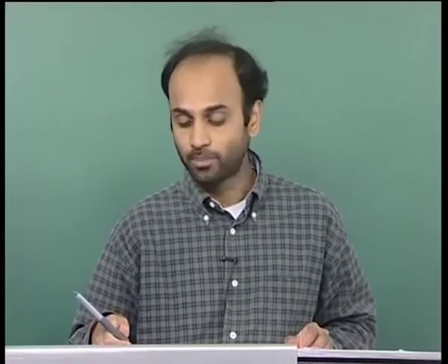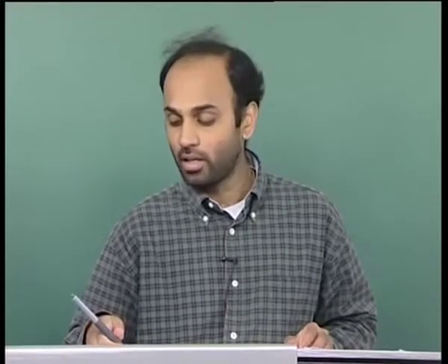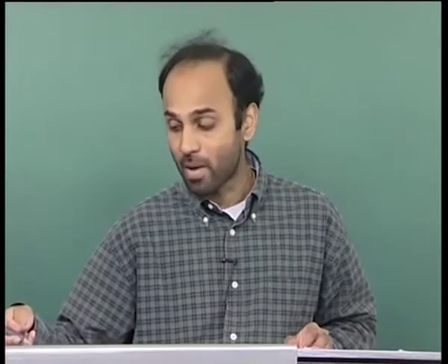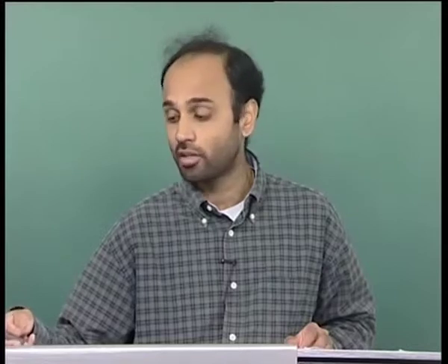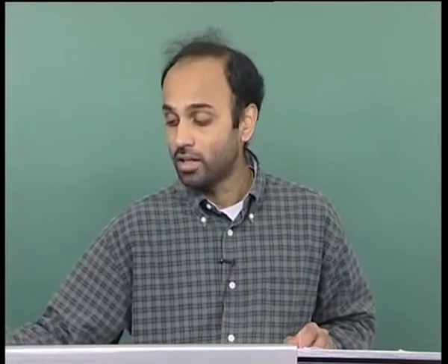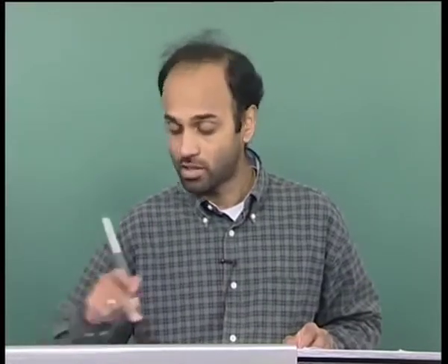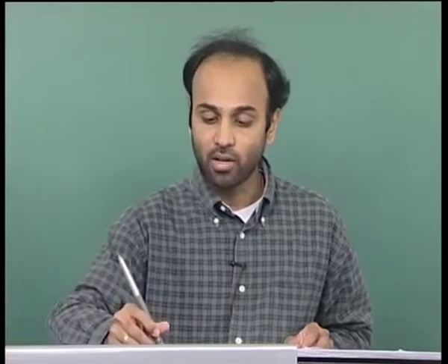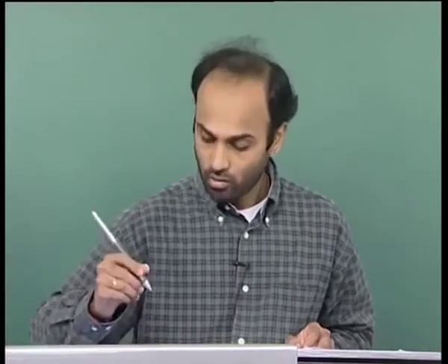So, we have now a very interesting relation. We said the correlation coefficient between the channel at t and t plus delta t can be derived as J0 2 pi f d max, the maximum Doppler shift corresponding to velocity v, times delta t, where J0 is the Bessel function of the 0th order. Hence, this gives me the correlation as a function of time. Let me show you a plot of this.